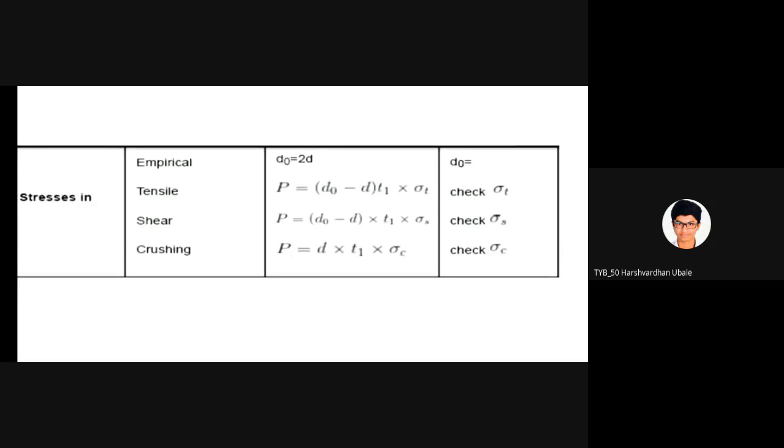So what we have to calculate is tau S, which is equal to the ultimate tensile strength of that rod. Are you going to write it? Yes, sir. Okay. So tau S or sigma S is equal to ultimate tensile strength divided by 2, and the whole divided by the factor of safety. So what is the ultimate tensile strength for the rod?